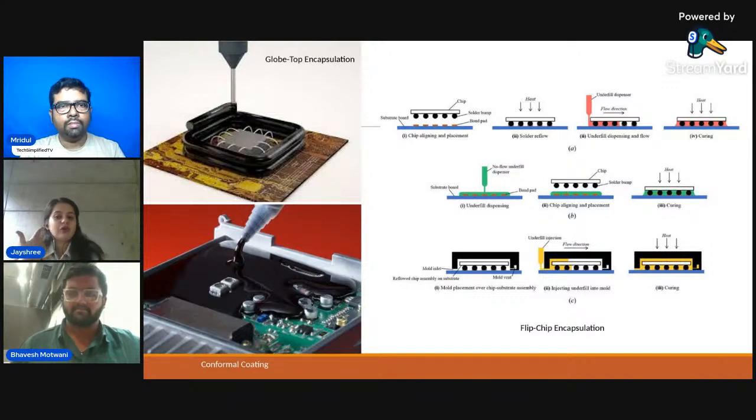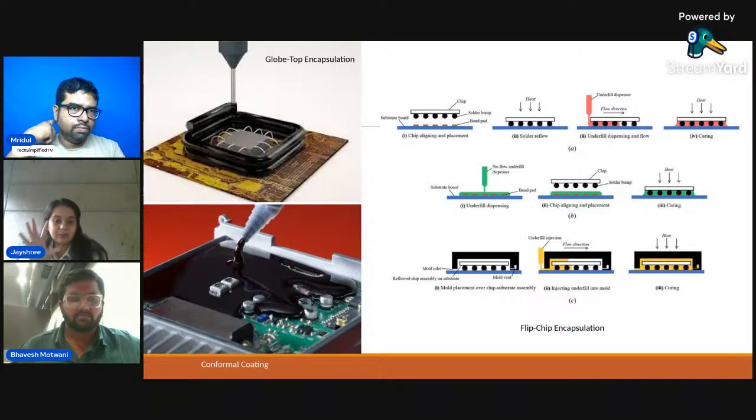The pros and cons of this flip chip are also limited. Pros is that it basically absorbs mechanical stress. We get the perfect encapsulated flip chip device. Eventually it prevents solder joint cracking also, and improves heat conduction. The limitations of this flip chip is that it's costly, the process takes time, and requires precise control flow. Eventually, it's used in high-end SoCs and mobile processors.